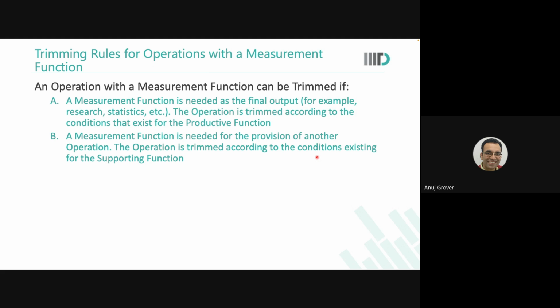So we have to think of ways in which, for example, you want to see what is the width of some part that you have made. Okay. You want that width to be lesser than something. So either you can measure that with a scale for every part, or you can say that a part will pass through this gate only if its width is less than that.